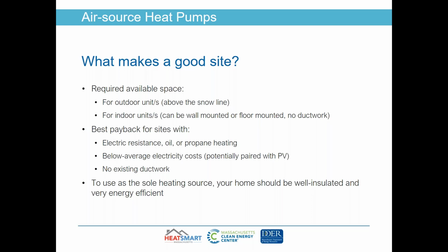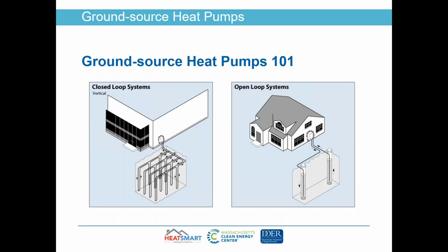And finally, to use them as a sole source of heating, the home really should be very well insulated, a tight envelope, minimal air infiltration, and just generally an efficient home. So they're very good and very common for supplemental heating and for cooling, but if you are looking to use them as a sole source of heat for your whole home, it does need to be a really tight envelope.